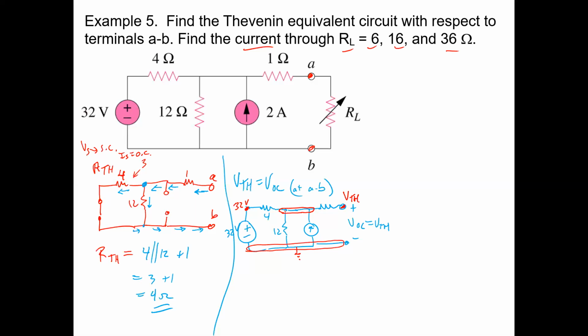Well, before you start calling it 24 volts, there's a trick here that can make this easier for you. Rather than calling it V1 or VA, you should look at this resistor here. This is a 1 ohm resistor. Ask yourself, if there's an open circuit at A and B, how much current is flowing through that resistor? 0, right?